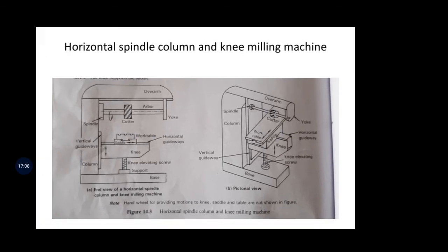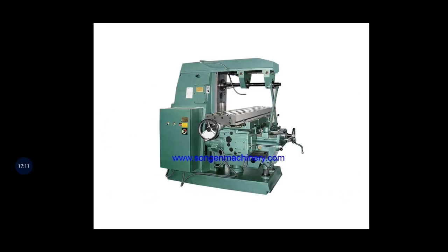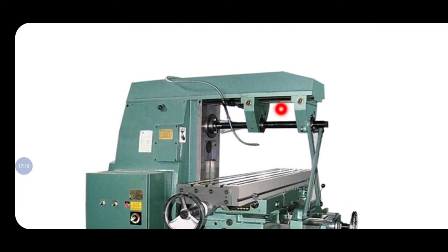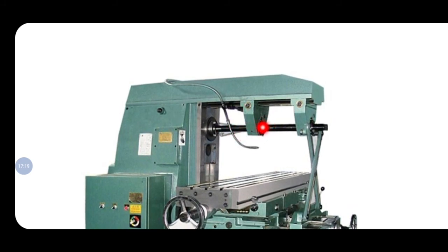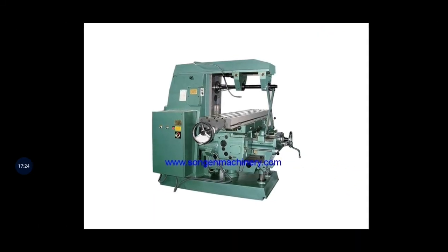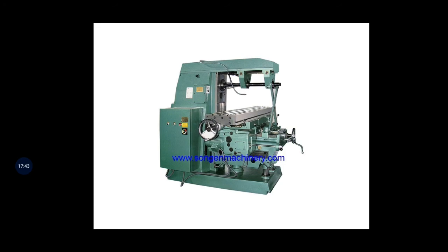Next we will go for the horizontal photo here. This is the arbor. This is the milling cutter. This is the overarm. This is the column. This is the base. This is the work table. This is a hand wheel. You can see the holes, T slots, and graduations. This is the knee. You can see the knee elevating screw here. All the parts. This is the saddle. Horizontal spindle, so the arbor is in the horizontal direction.